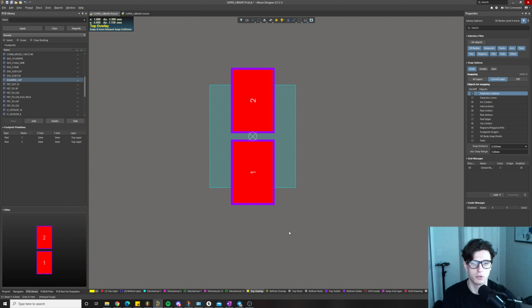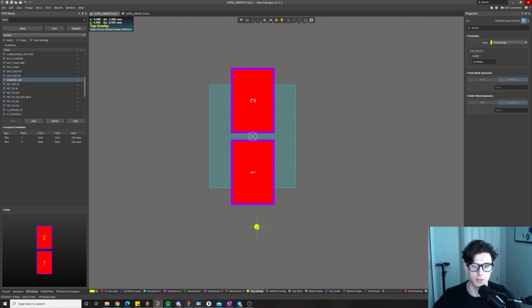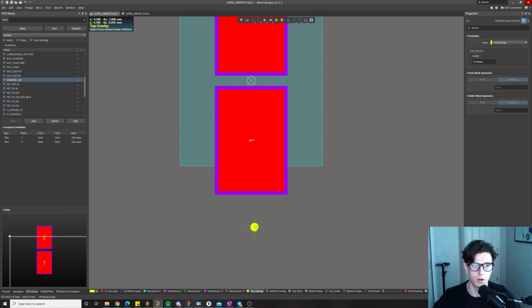So we're going to make a little note here but we also have to make sure that it carries over to when we do our schematic. So we're going to pick pin 1 as the polarized one. We're going to do place, and then we're going to do arc, or full circle, I should say. So if you make your arc width thick enough and then you make the circle small enough, it turns out to be just a dot. So we're going to go right about here and then see how, yeah, just like that. And then boom, it's a dot.